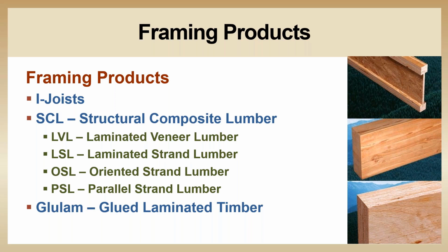This is a family of engineered wood products which are created by layering dried and graded wood veneers, strands, or flakes with moisture-resistant adhesive into blocks of materials known as billets. These billets are then resawn into specified sizes.